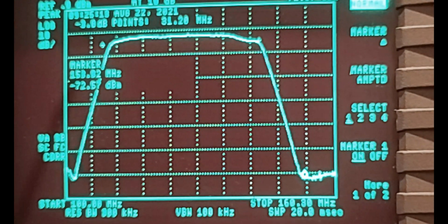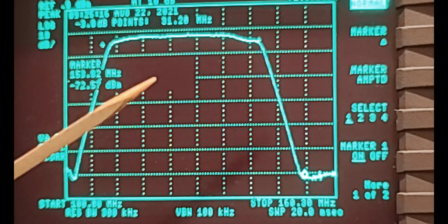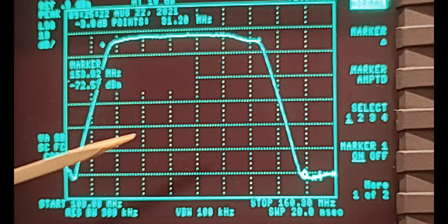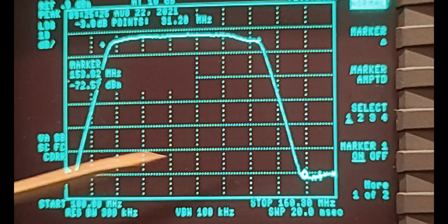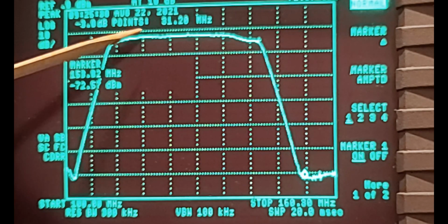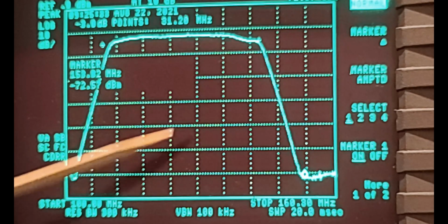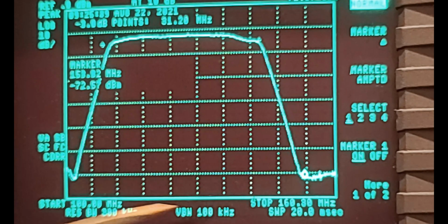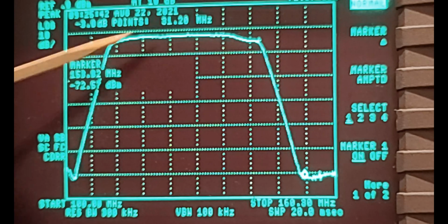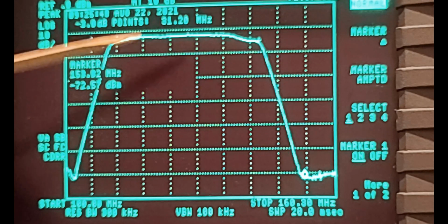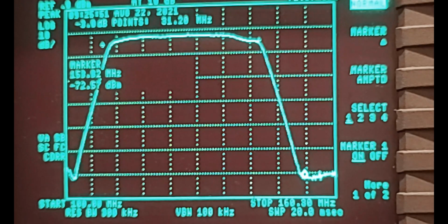So anyway, that's a quick view of using a sweep generator to build a frequency response plot to do measurements on your filters. Now, if you want to do filter tuning as in a duplexer, you would follow a similar workflow, but if you need to tweak the waveform to a particular response, then the process becomes iterative and you would have to go through the cycle. We only did this one cycle for us to build this plot. But if you were to do tuning and tweaking of your filter as in a duplexer, then the process becomes tedious, iterative and time consuming.